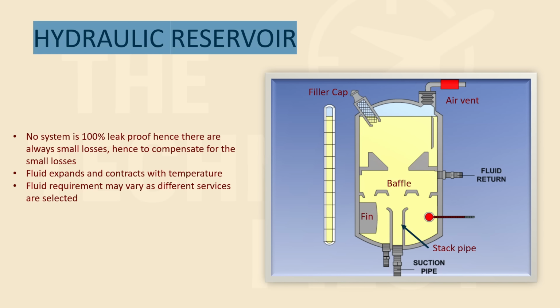Then in system components, there is the hydraulic reservoir. The hydraulic reservoir is the thing that stores hydraulic fluid. Why do you want hydraulic fluid to be stored? The reason is, since no system is 100% leak proof, there are always small losses. And to compensate for small losses, we need a hydraulic reservoir.